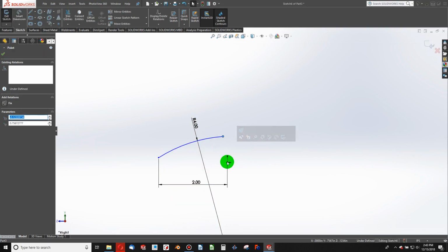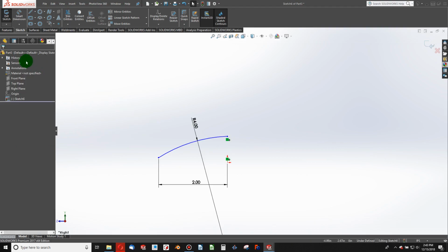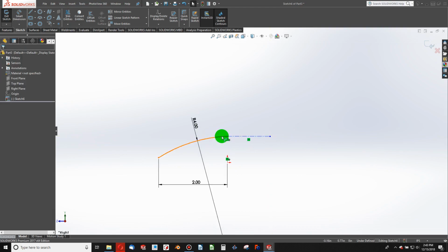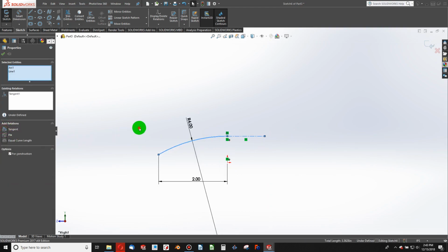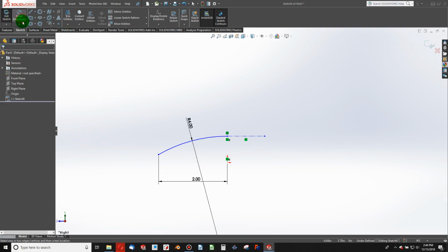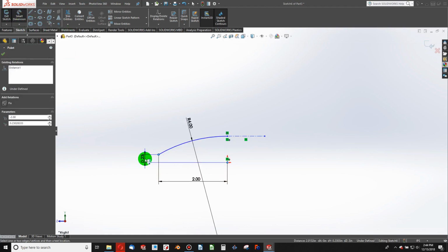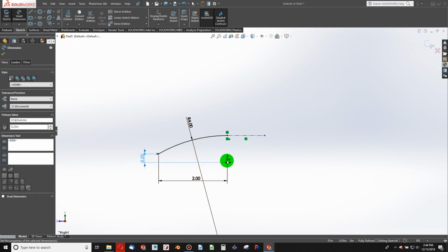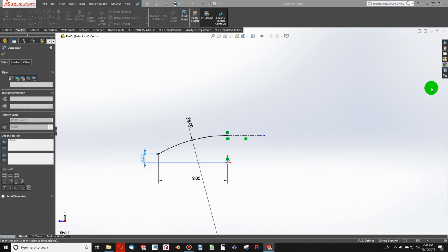We'll make this not only vertical with our origin, but I think I'll also make this the tallest point of the mouse, which implies that my curvature at this point will be tangent to horizontal. Now I'll give the front end a height and make it something like 1/4 inch. And we'll say that this origin kind of represents the bottom of the mouse, or where the mouse is going to sit on the desk. Maybe we'll make this a little bit taller, maybe 0.4.